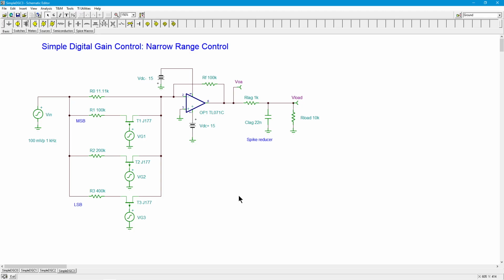If you're familiar with this, you might be saying, well, could I configure an R2R ladder network? The answer is yes, you could. You could do that, in which case I wouldn't go with FETs. You'd actually need 2 FETs, one to engage and one to switch over to true ground rather than the virtual ground of the summing node. You're probably better off getting an analog switch that's single pole double throw, an SPDT, so that the switch would be throwing either to true system ground, or to the virtual ground of the summing node, instead of just interrupting this. That would be required for the R2R.